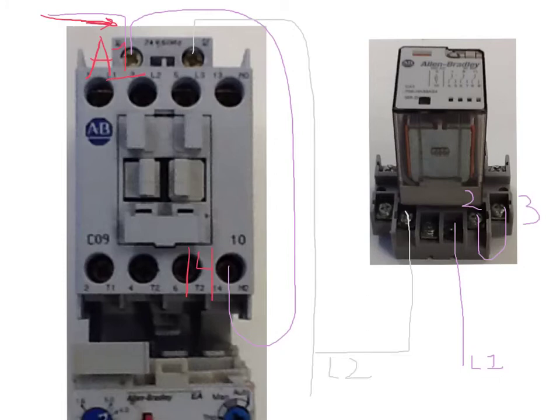The same is going to be true over here on our control relay. I've got this jumper drawn over here on 2 to 3, just a short little wire. And again, we've got power on 1 because we're going to use an open contact. So in this case we're using the contact 1 and 3. And what that contact's going to do is provide a bypass so that when those momentary contacts open, we are going to maintain our control circuit.